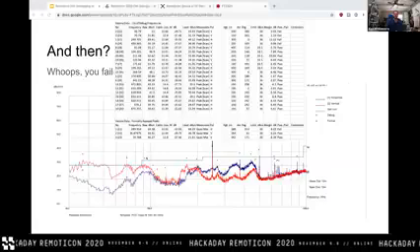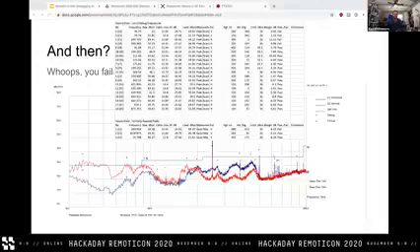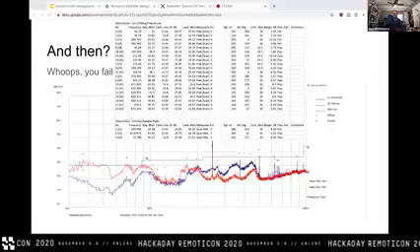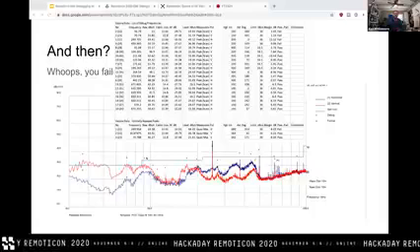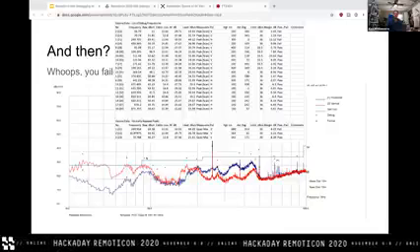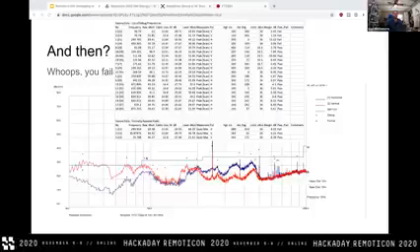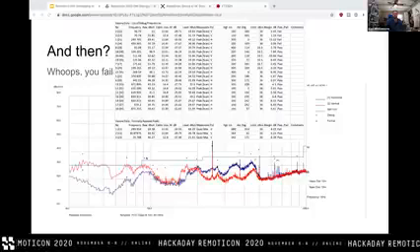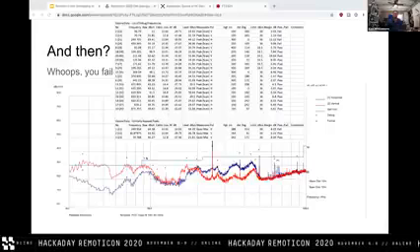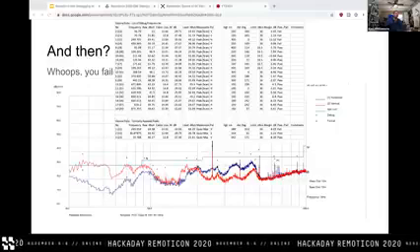Well, devices behave differently throughout time, and maybe your device is chirping really loudly for a moment, but it doesn't do that all that frequently. Maybe your device only makes a loud burst of 250 megahertz when it first turns on or something like that. Or maybe it does it for 1 millisecond every 100 milliseconds. And it turns out that doesn't actually really cause any interference on any adjacent devices. So even though the peak is really high, the power that matters as far as causing interference isn't actually that high.